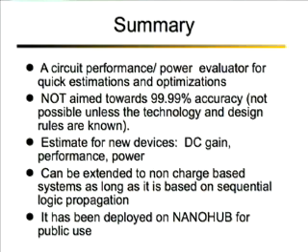So we can do an estimate for the new devices for DC gain as well as power performance. And finally, we can also extend it to non-charge based systems as we go in future, as well as there is a sequential propagation of logic from one stage to another. At the moment, what this tool can provide are good estimates of delay and power in a typical CMOS design environment, where the transistors are just drop-in replacements of CMOS transistors.